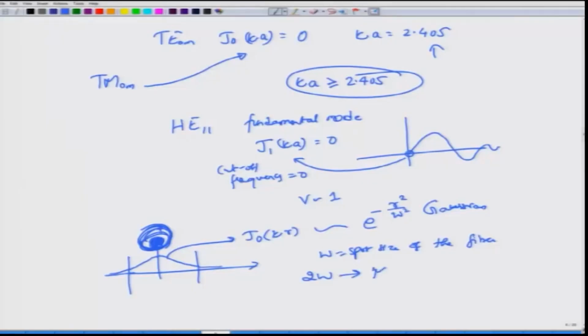And this spot size is important because if one fiber has an extremely large spot size and you then go with a fiber whose spot size is very small, when you try to couple them, the light is spread out much more widely in the first one because of the larger spot size, whereas the light collecting capacity will be smaller for the second fiber because it has a smaller spot size, and there will be a spot size mismatch. Twice the value of spot size is what we call the mode field diameter.